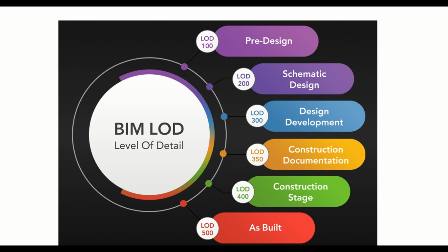So for that duct, for example, one support is placed, and again another support will be placed at 1.5 meters, 2 meters, and that will be shown on the layout as well. I guess that's clear on LOD 400. Also, LOD 400 will sometimes go to off-site prefabrication shops, because the support that I was talking about will be assembled in the prefabrication shop, not on the site.